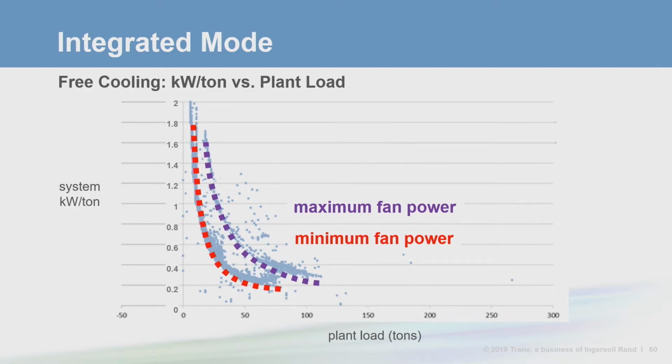see quite a number of points when the minimum fan power was achieved, yet the efficiency was far worse than expected. The most disturbing thing this graph reveals is that even at minimum fan power, there comes a time when the efficiency of free cooling is horrible, 2 kW per ton. Why is that? For one thing, the tons are too low for kW per ton to look very good. Also, we don't have wet bulb on this graph because it's only 2 dimensions.